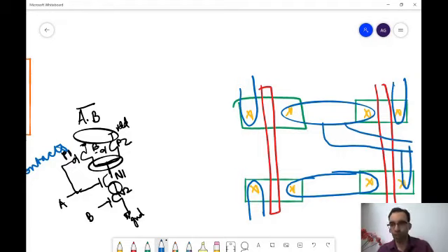So what is happening now? How many capacitances do we see? If we just count poly to contact capacitances, there are 1, 2, 3, 4, 5, 6, 7, 8. 8 capacitances from poly to contact. Additionally, there are 8 source and drain capacitances also.